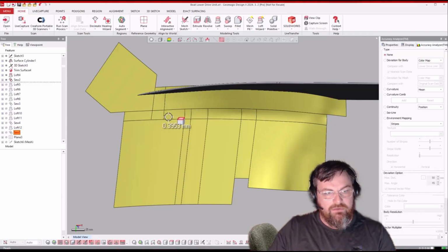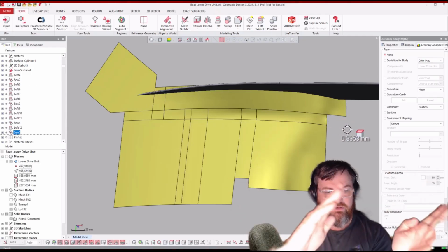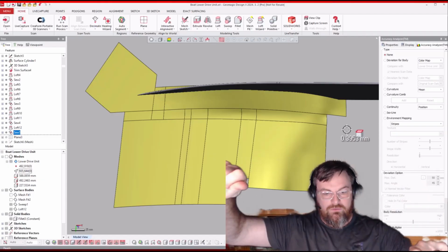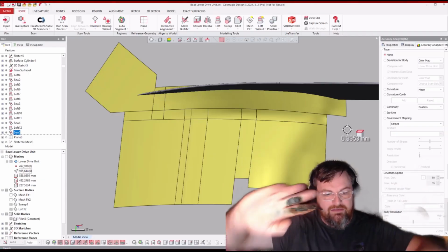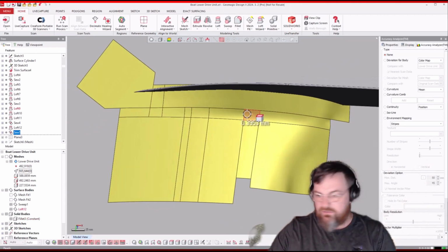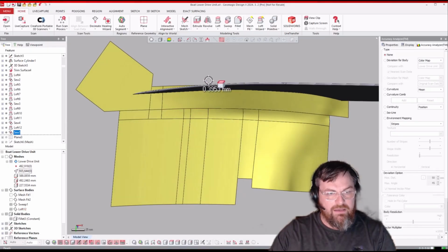If you try to do that all in one from edge to edge, a lot of times you'll have it stretch and streak, and it's like taking a piece of fabric and pulling it and making it stretch in an awkward way. That's the same thing with these NURB surfaces because they want to be four-sided patches. Yes, you can trim them in different fashions and make them a trimmed surface, but underlying it's still using four-sided NURBS patches with trimmed edges.